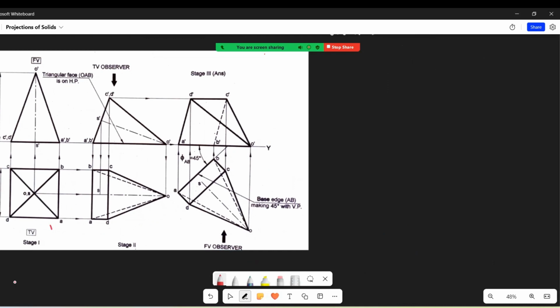This will be the view number 1. That is, we will draw this view first. Then we can draw this view. Then the third position is obviously this. Fourth position is this. Fifth position is this. And this will be the sixth view that we will draw. So it is important to identify the position number 1, and then the remaining positions are drawn in a sequence.